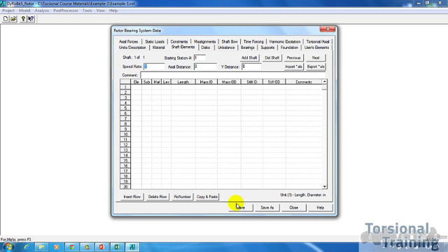And in order to start that, you first develop your element. So in this case, we're only going to need one element, since we're just trying to check the torsional inertia and the torsional stiffness calculated by Dyrobes, and we're then going to go ahead and compare what we calculate with respect to a hand calculation. So without much further ado, under the element column right here, click there and hit element number 1. So this is the first element, so it'll be element number 1, and under sub, click on type in 1